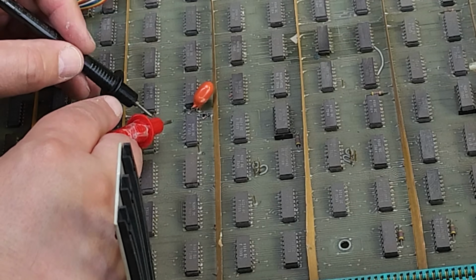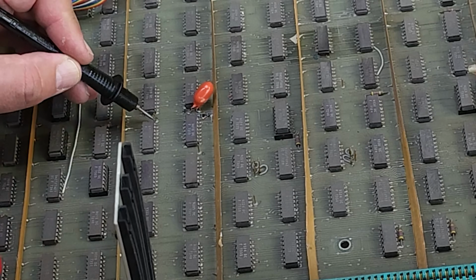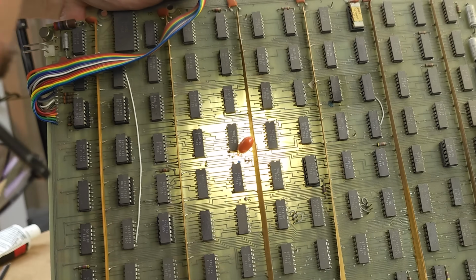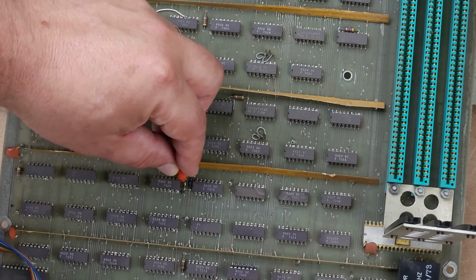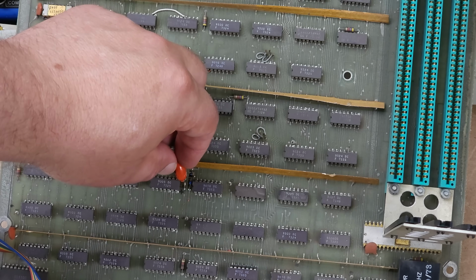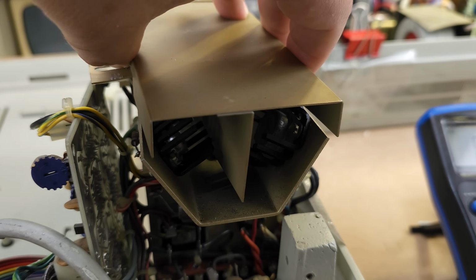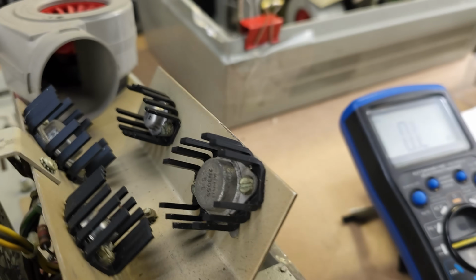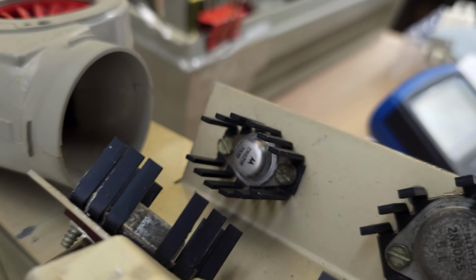With the board out, I can recheck and confirm some of the voltage rails and see how that lines up with the power supply. And that's when I discover a tantalum cap that has a leg broken at one end. I'm going to order a replacement part for it, but for now I actually think I can reattach the broken leg pieces with some solder. Okay, yeah, it seems to be charging okay for now. Here's a closer look at the voltage regulators with the tunnel hood removed. Some are a little rusty, but testing doesn't reveal any shorts.